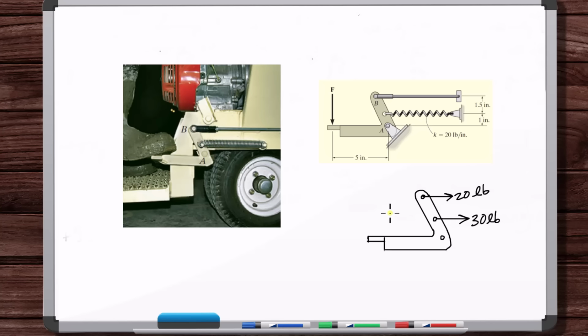But again, you have to put the correct knowns, and you have to be careful that you apply as many knowns as possible. If it's unnecessary to put an unknown theta here, to call this an unknown theta, it's effectively horizontal, then don't do that. Don't put an unknown theta. Make smart assumptions. But if you have to have an unknown theta, then do it. Okay, so we've got the force magnitudes and directions and also their positions. We're not going to just put this force here. No, we know its position. Its position's there. So get all of the known information right: force magnitudes, directions, and positions.